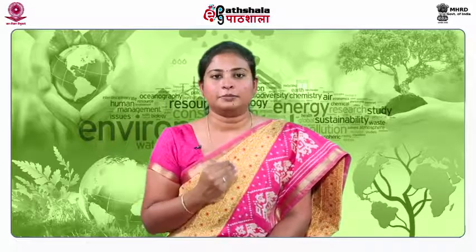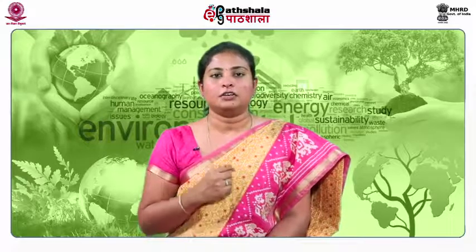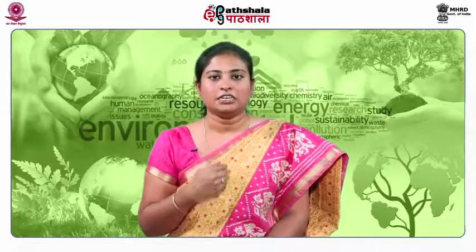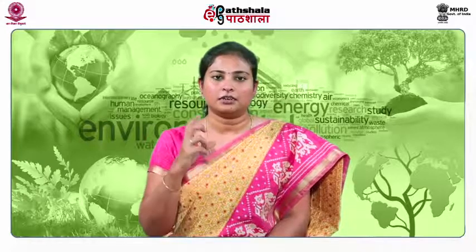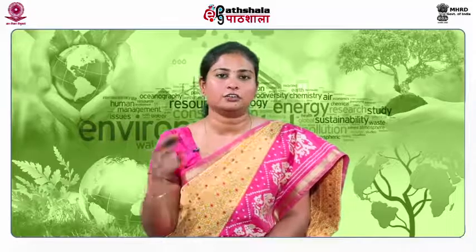The next component is the daily and final cover at the top of the landfill. The cover protects against the entry of water into the waste during precipitation. The cover layer is composed of synthetic and natural materials. For daily cover, about 150 mm of soil is placed on each layer of waste.